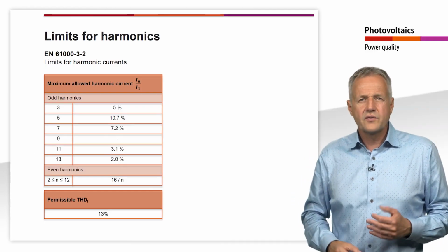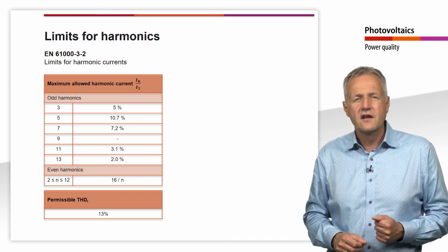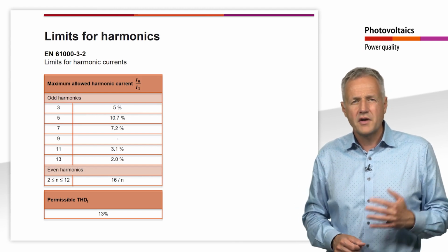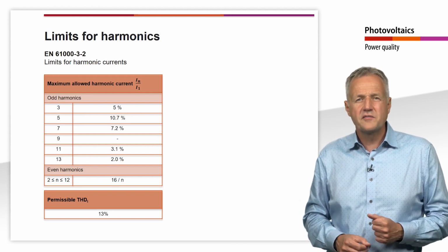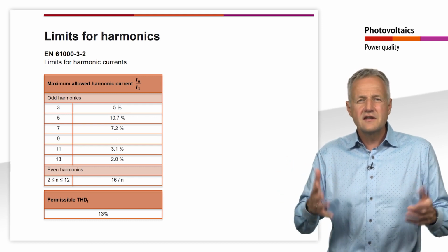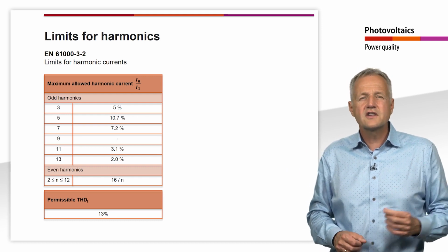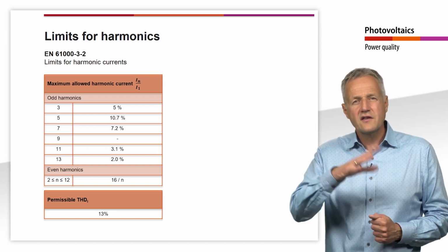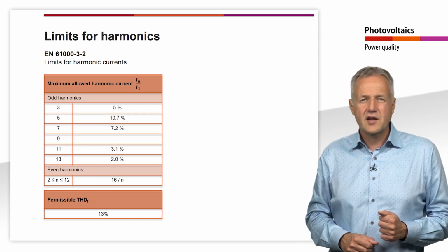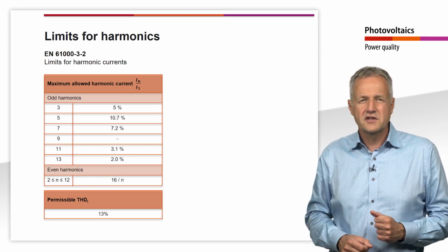An AC current with a high proportion of harmonics can have various effects. The harmonic currents do not contribute to the active power, but generate additional reactive power that oscillates back and forth in the grid. This leads to additional heating of the lines and consumers. In addition, harmonics can cause resonance phenomena in oscillating circuits consisting of coils and capacitors, which can lead to very high harmonic currents or voltages.